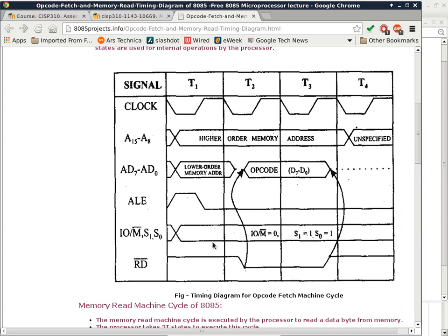You can see from the bar on top of RD that it is an active low signal. When the signal is high, when you use a voltmeter, it means it is not asserted, it is not reading. When it's low, it is actually reading. It's called an active low signal. And active low has a lot to do with the type of transistor we use in the processor, which typically are the N-type, or NPN in the good old days, but now it's called the N-type MOSFET. Because of the substrate, it's the less expensive of the two, because you can have an N type or a P type. The N type is the less expensive one, and it lends itself to active low signals. So that's partially why we have that sort of thing.